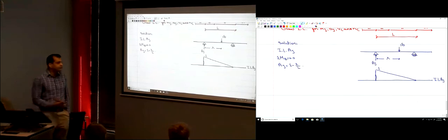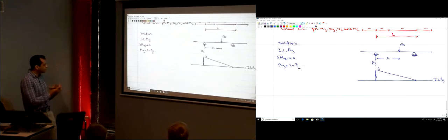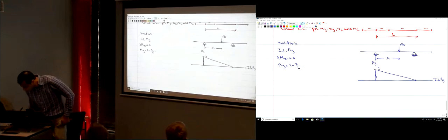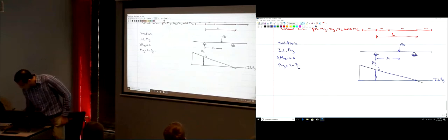Let's draw this function. The influence line of AY is 1 minus x bar over L, so we did this before. It looked 1 here and 0 here, so this is 1. But now the influence line is extending over the overhanging parts, okay? It's the same equation, just a linear equation, 1 minus x over L. So it's the same line, you just have to extend it from here.